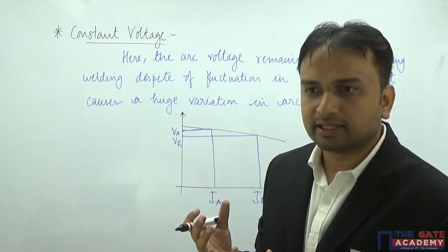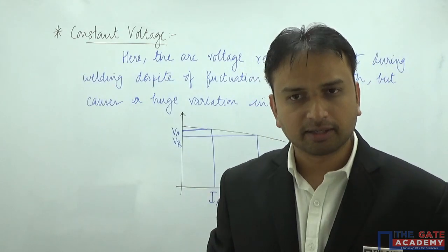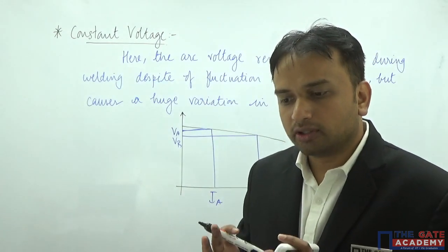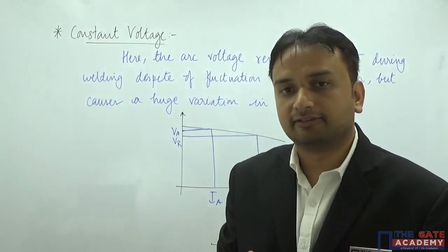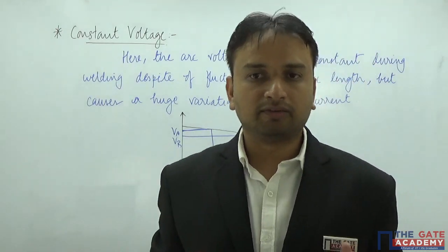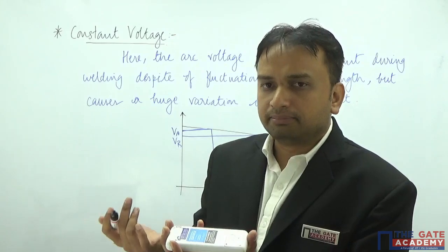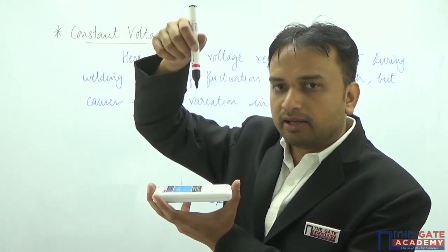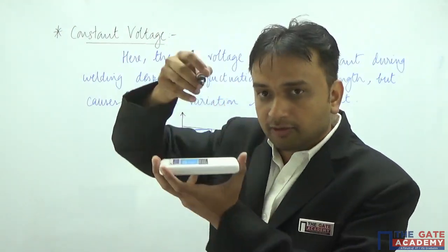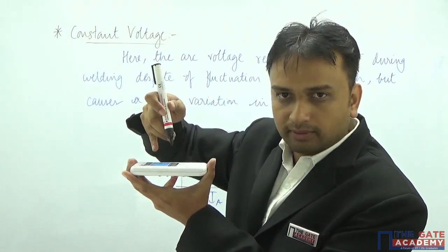But sometimes the machine also makes some errors. There are certain errors in the computation also. So if you have automated the machine and you want the machine to take care of itself on its own, and you do not need to interfere, then you will develop a self-correction mechanism for the machine. So let's say by error, this servo controller fed the electrode wire too much. A lot of electrode wire was given, and because of which the arc length, which was supposed to be like this, has come down like this. Are you getting the point?